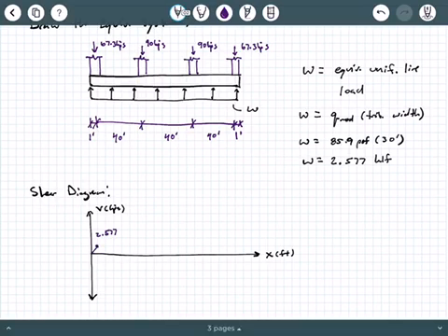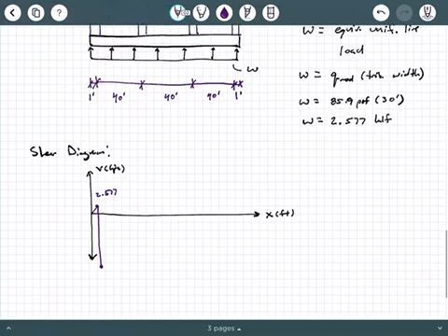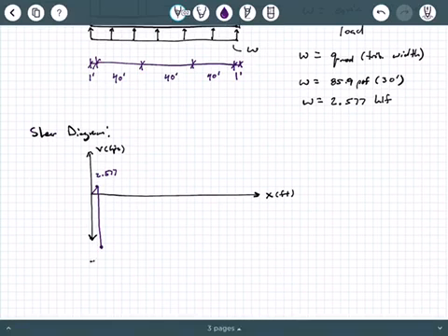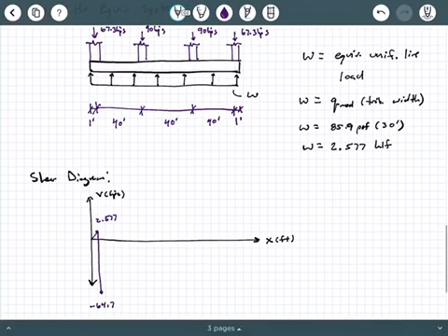And then we're going to say minus 67.3 kips, okay? And when we do that, we're going to jump way down here to negative 64.7 kips, okay? And then we encounter a 40-foot spread, that's right here, center to center, 40-foot spread of the 2.577 KLF, pointing up.